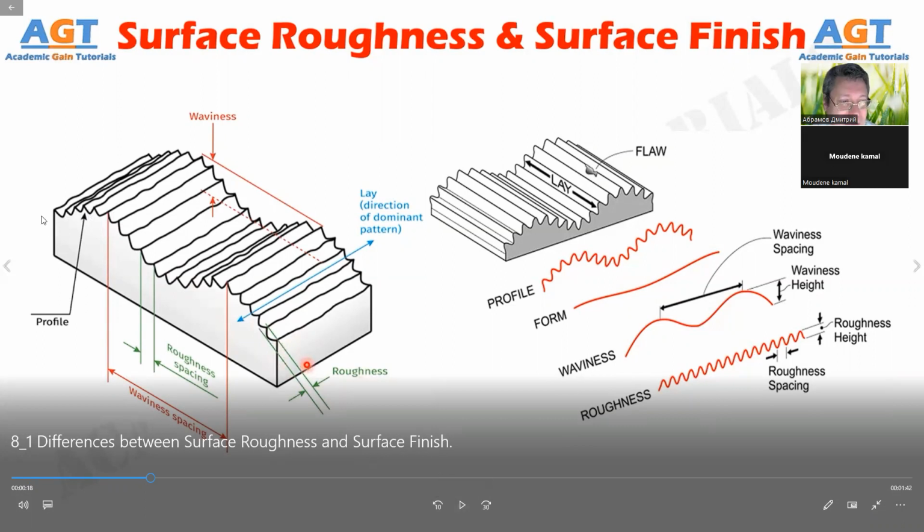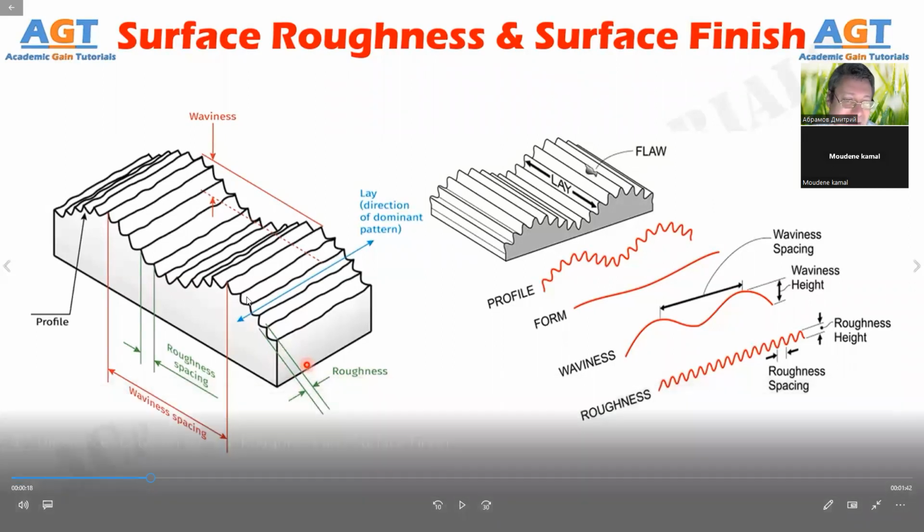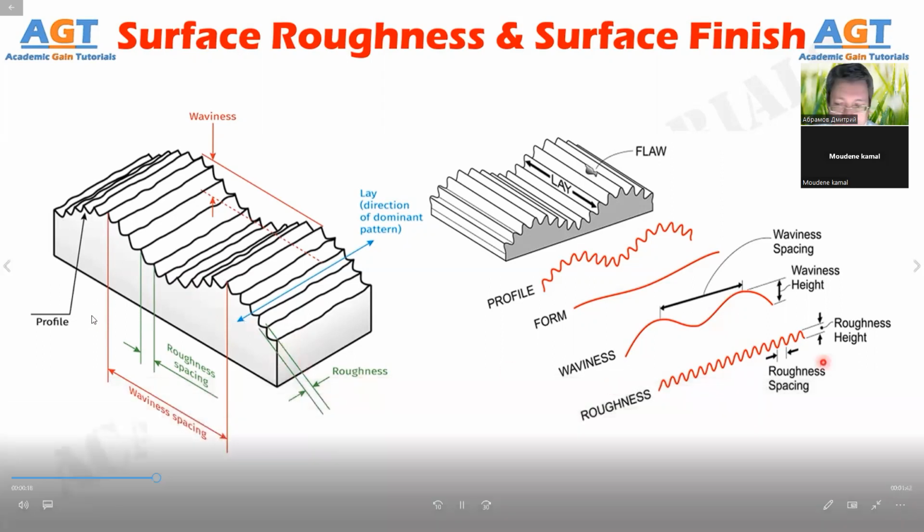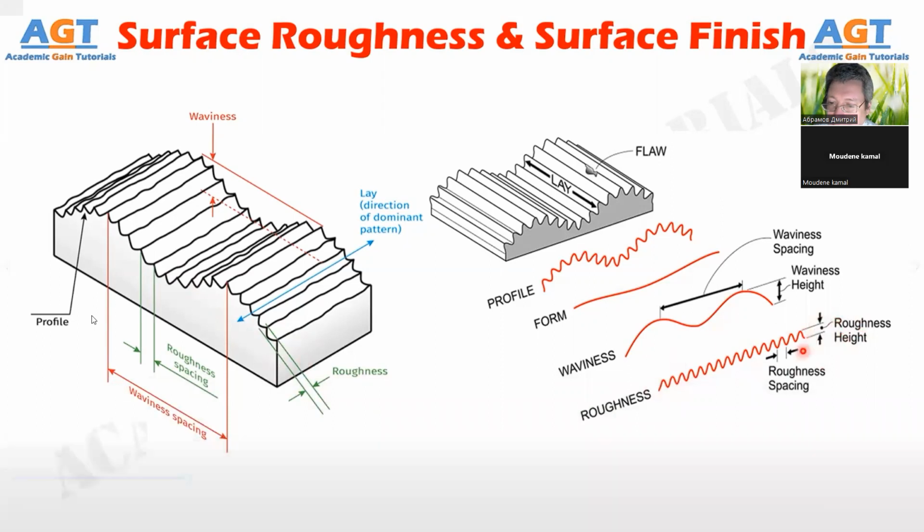At the macro level, it will be waviness; at the micro level, it will be roughness. Surface roughness refers to the height of macro and micro asperities and irregularities present on a finished surface after machining, while surface finish indicates the quality of that surface using various attributes like fine, rough, good, poor, etc.